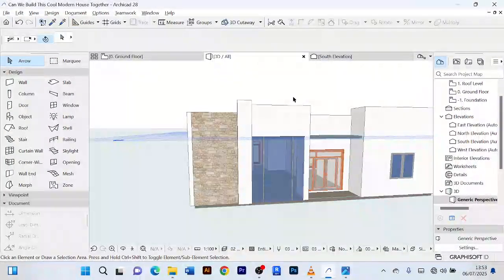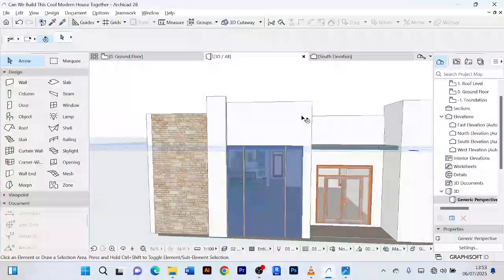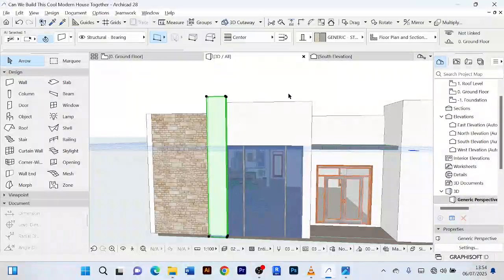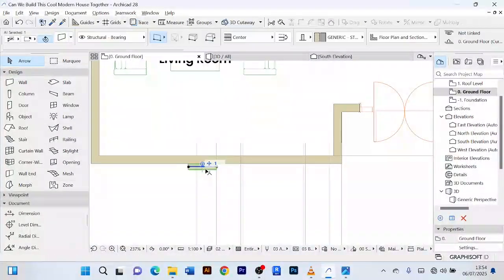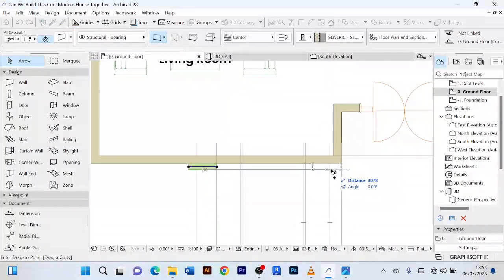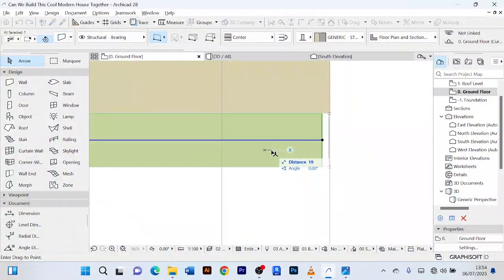Then there's something we're supposed to do on this part here. We're going to also draw this kind of wall here. I can even duplicate this. I'll click on this and say Control Shift D, which is to drag a copy, and I can bring it here just like that. However, it is going to be a little bit smaller. When I Control D, I can drag it and bring it here, just there.